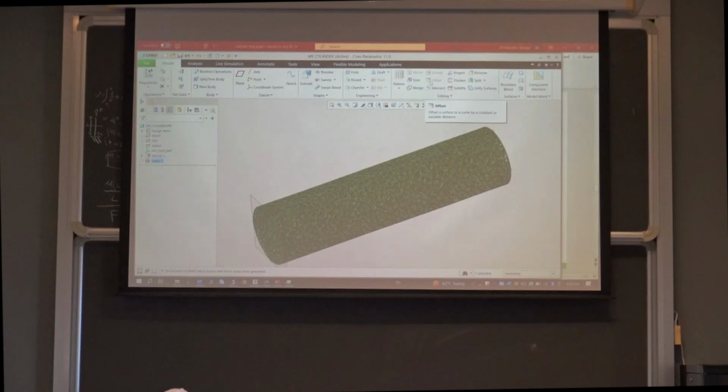Now imagine that we put such a thing inside a pipe. So fluid goes from one end to the other end. The question: is it a good filter design or bad? The answer: it is bad. Why? Because all pores are absolutely the same size. So the entry layer of this filter will be contaminated almost immediately, and the filter will be clogged. And the whole remaining volume of the filter will be almost clean.